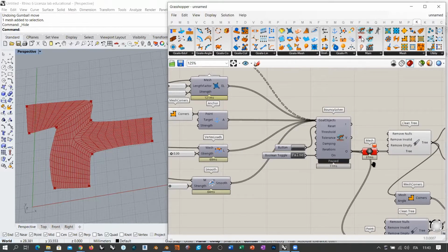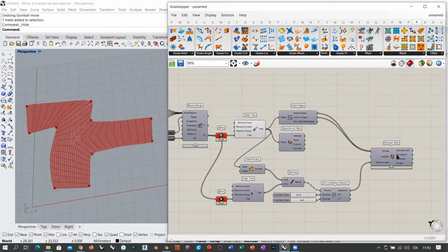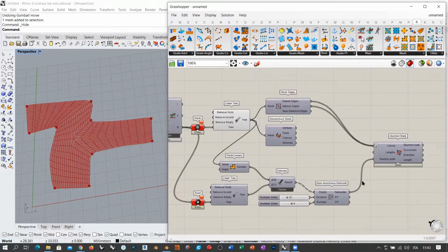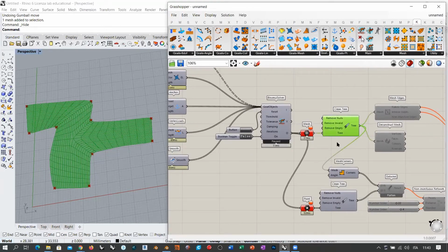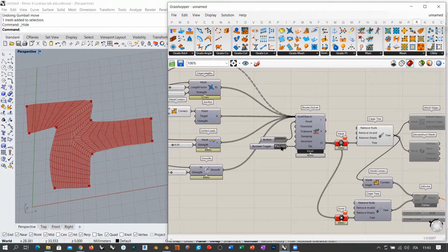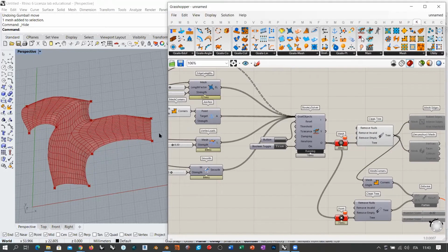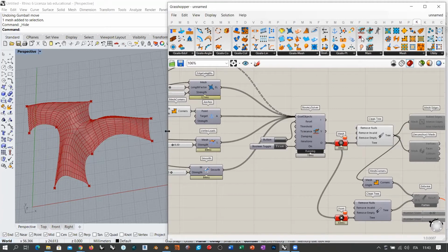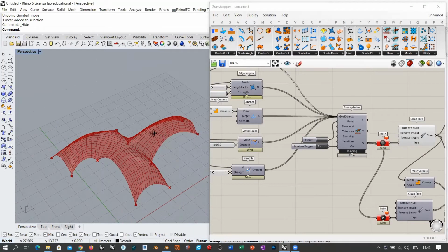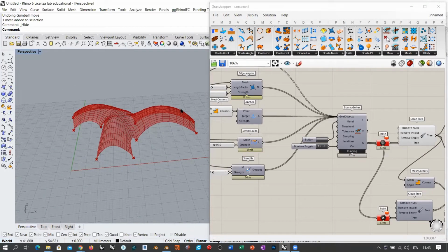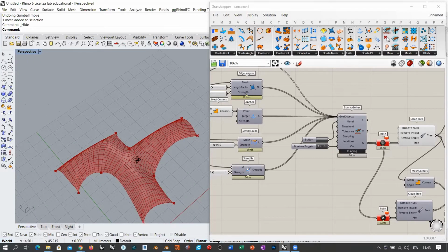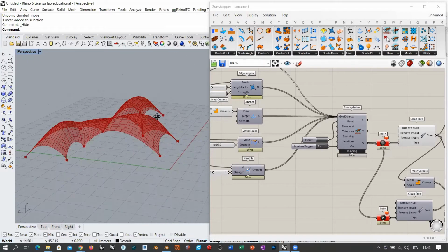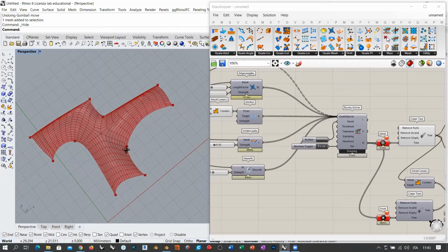I think this thing here is making things run slower, so I would deactivate all the last part of this definition. I'm only interested in the deformed mesh. So when we run the simulation now, we will have some smoothing occurring, and we should see that this mesh no longer has those creases appearing along the way. Okay, so you see that we get an extremely smooth result.